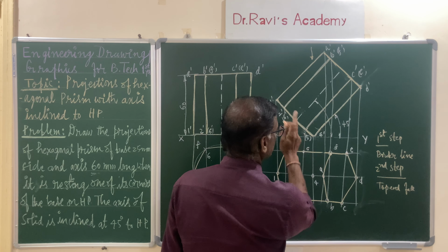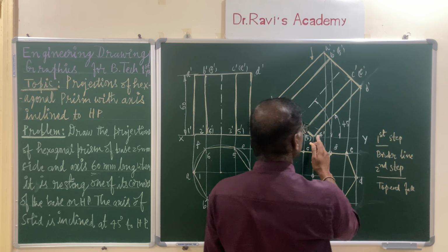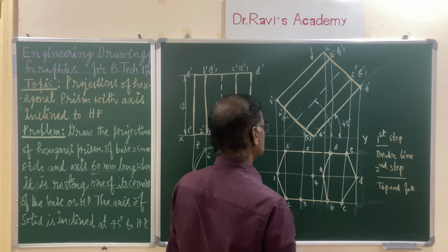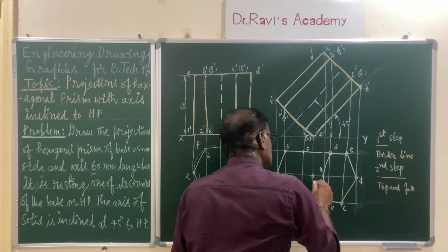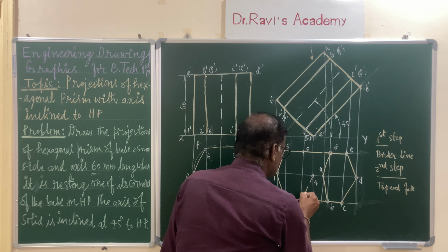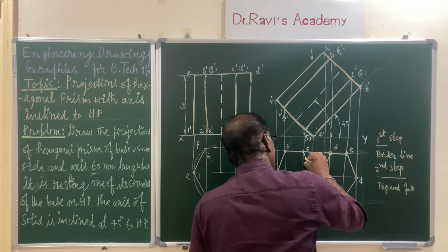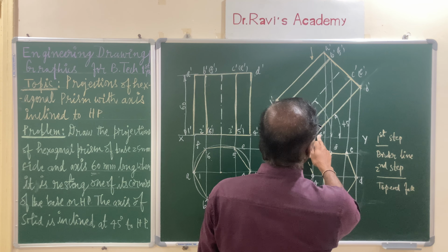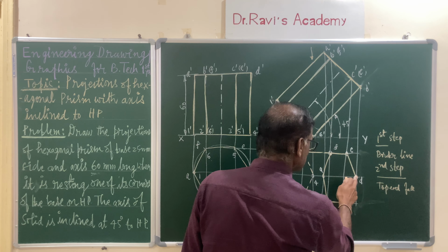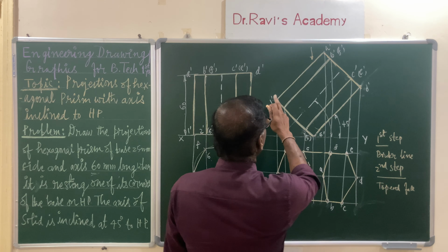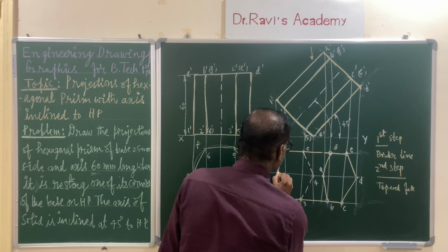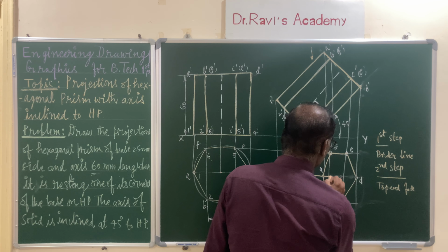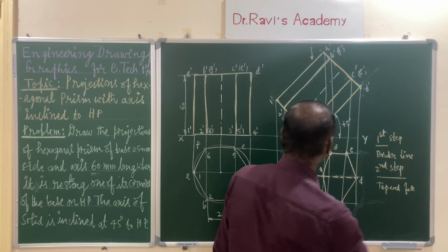3, 4 and 4, 5 base edges. Similarly, 4D also, the longitudinal edge also not visible. So, this you have to join with the dashed line. So, it is a 3, 4, you have to draw 4 to 4, 2 and 4, 5, this is also you have to draw 4 to 4, 2 and longer edge of 4D. So, 4D is hidden, but observe carefully your 1A is visible, and this portion which is hidden you can mark with a dashed line.